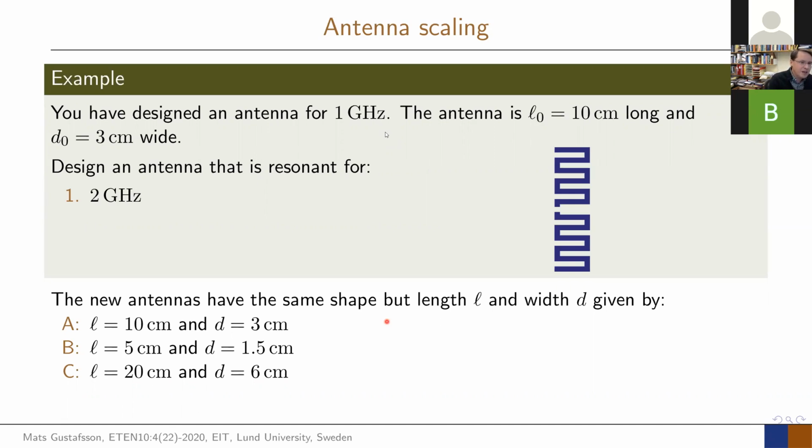And this is, again, one of those cases where it's really good to have the idea of, for example, 1 gigahertz, 30 centimeters. Okay, I want it now at 10 gigahertz. Okay, that's 3 centimeters. And you scale your antenna with this number of wavelengths.